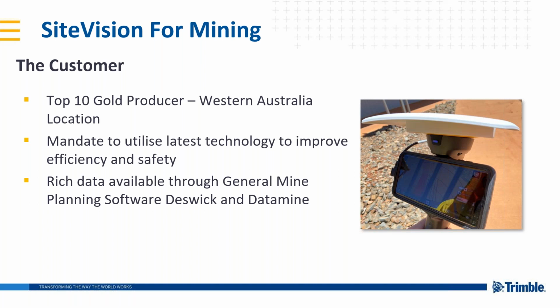So the first problem we had to overcome was taking that data and getting it into SiteVision. The workflow we developed was to go from DXF, from the mine planning packages, into Trimble Connect and then onto the device. This can be achieved in a few ways. They're looking at setting up teams with Trimble Connect so data can be sent to the survey team or the geology team and so on.